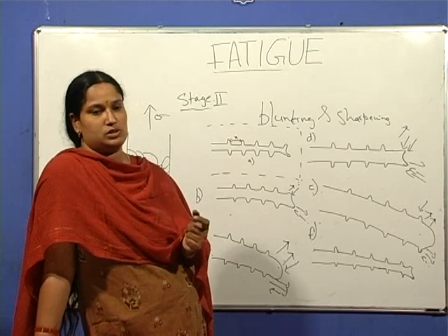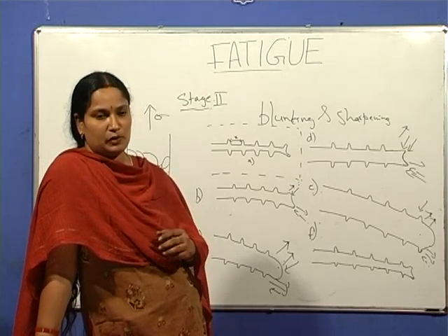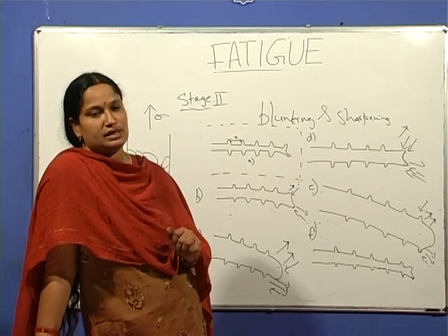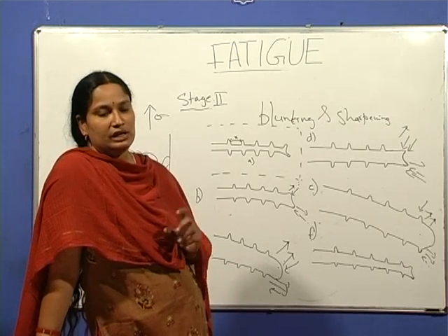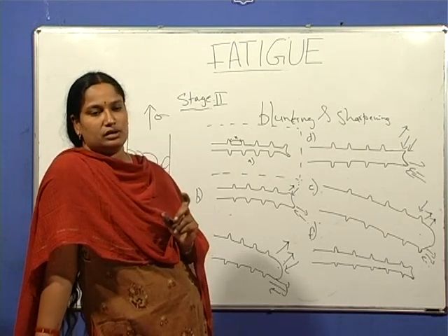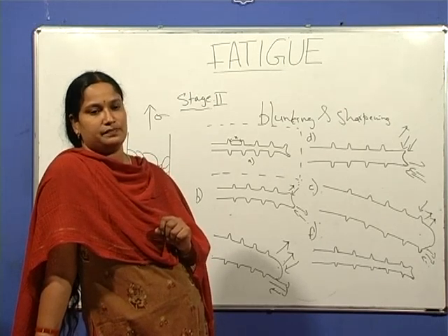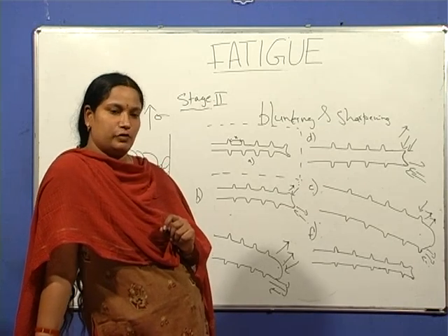So, these also act as stress concentrators. During the manufacturing process, if the applied stress is compressive, then it leads to residual tensile stress on the surface, which lowers the fatigue life of the material.